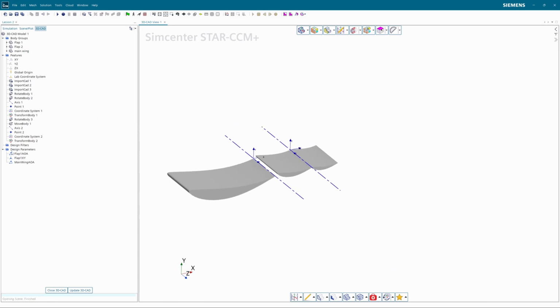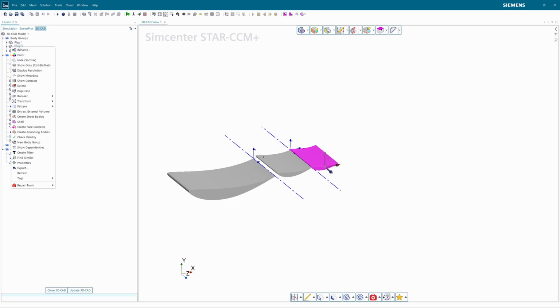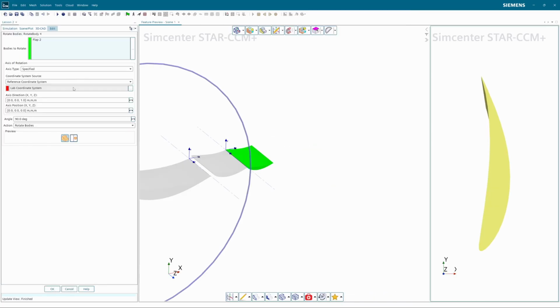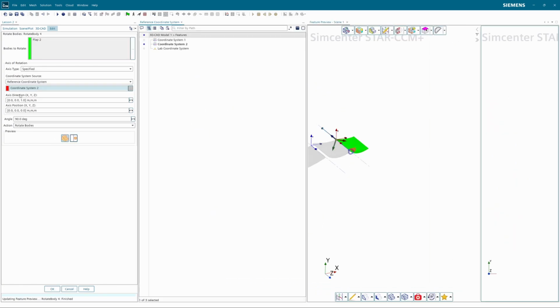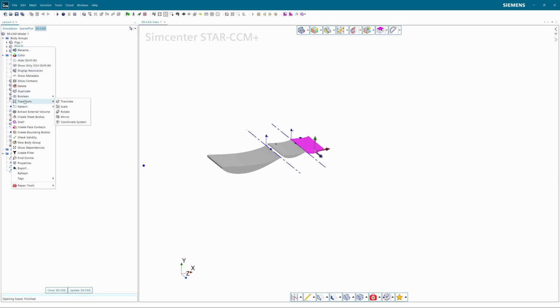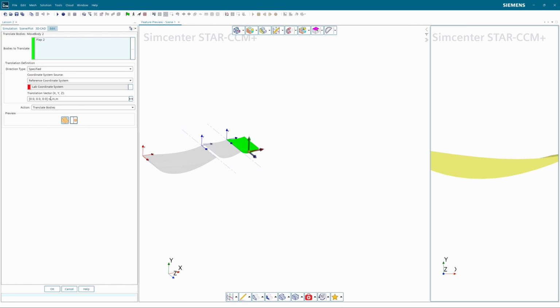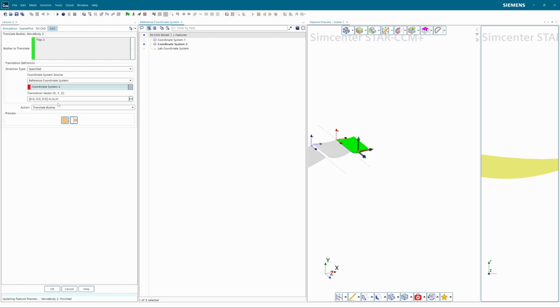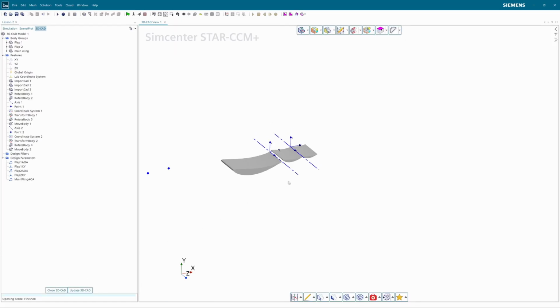And we're also going to add an angle of attack transformation to this one. Transform, rotate in this coordinate system, 0 degrees, expose parameter to AOA. Okay. And one more translation. Transform, translate. Okay, so now I have properly parameterized this.